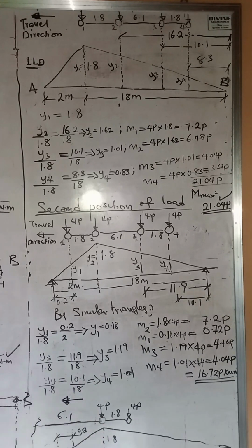By the time we place the axle load at that point, you will observe that the first and the second axle are already out of the beam. So we're only left with axle 3 and axle 4. And of course, axle 3 and axle 4 only have 2 point loads, and these 2 point loads cannot produce moments that will be greater than any of these two we have treated before now. So by that, we'll conclude that putting axle 3 at that point 0.1 L is not necessary. It's just a waste of time.